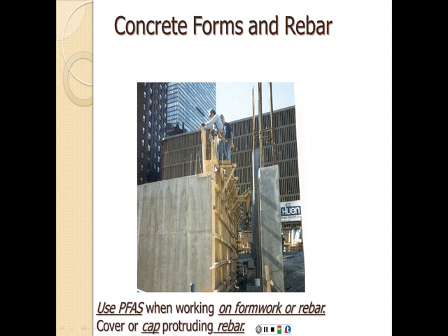When working on concrete forms and around rebar, to place rebar or to work on concrete work, use PFAS, which is the Personal Fall Arrest System. When working on formwork or rebar, cover or cap protruding rebar. So the rebar itself has to be capped to prevent the hazard of impalement. If someone falls on the edge of the rebar, that might penetrate through their chest or their midsection and can cause severe injury or even kill them.